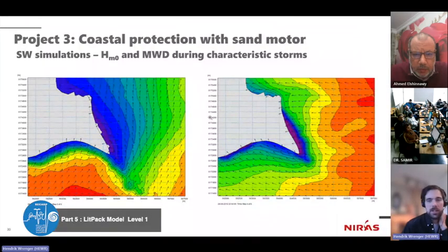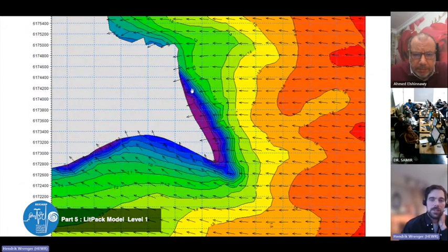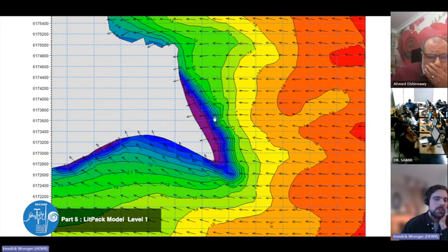And then the other characteristic storm that we get at that site is the easterly storm. Sorry, maybe I said westerly before. It's of course a storm from the east. So here it's perfectly fine to have the profiles along the east coast, right? When we assume offshore conditions here, then we just get the shallow water transformation along the profile. There is no diffraction happening here, right? The direction hardly changes, and it's probably due to refraction. But then we're making the mistake here on the southern coast, where we get heavy diffraction around this headland again, which is also extending underwater.